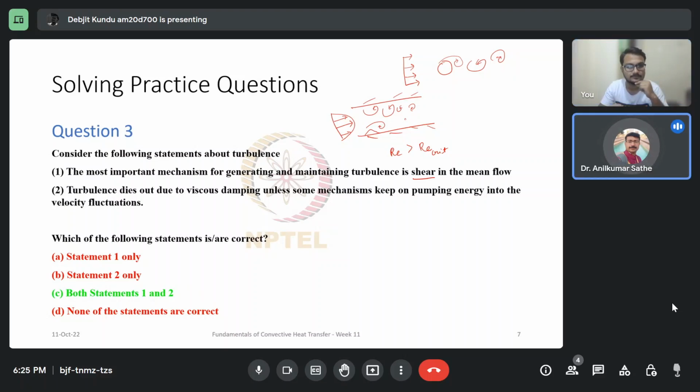But at the same time, there is a pressure drop because pumping power is extra. So I did calculations for pumping power also by connecting a U-tube manometer across the inlet and outlet. For that pressure drop, I used the Darcy-Weisbach equation. Enhancement ratio means the benefit we are getting at the cost of pumping power. So that enhancement ratio we determined, and an optimal system was designed as a result. The outcome was an optimization. Very interesting.